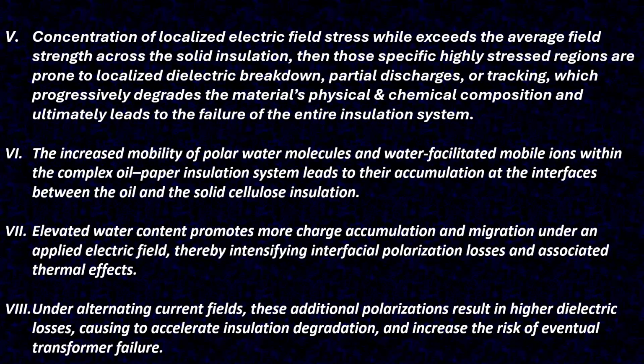When the concentration of localized dielectric field stress exceeds the average field strength across the solid insulation, then those specific highly stressed regions are prone to localized dielectric breakdown, partial discharges, or tracking, which progressively degrades the material's physical and chemical composition and ultimately leads to the failure of the entire insulation system.